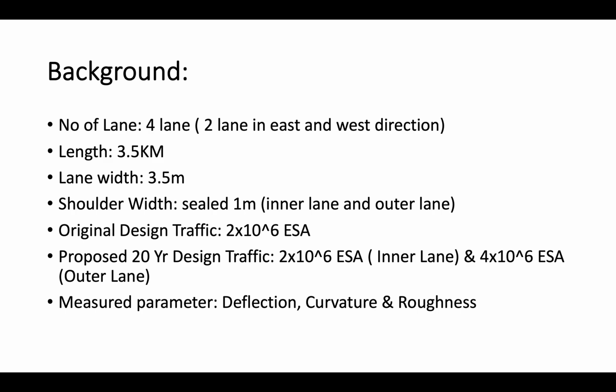The original design traffic was 2 multiplied by 10 to the power 6 equivalent standard axle. The new design proposed was the same for the inner lane, but for the outer lane it has been doubled. The parameters that we measured were deflection, curvature, and roughness.